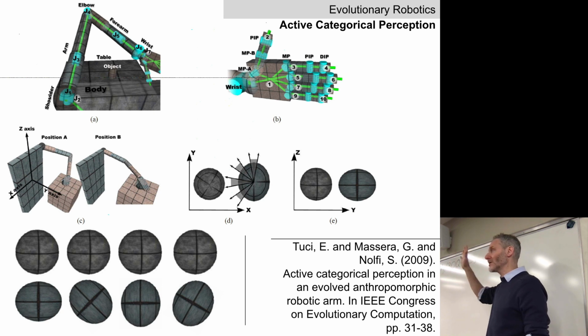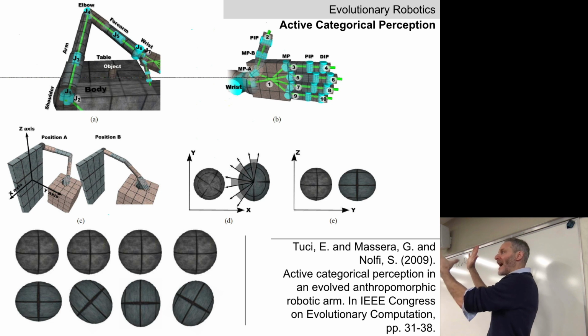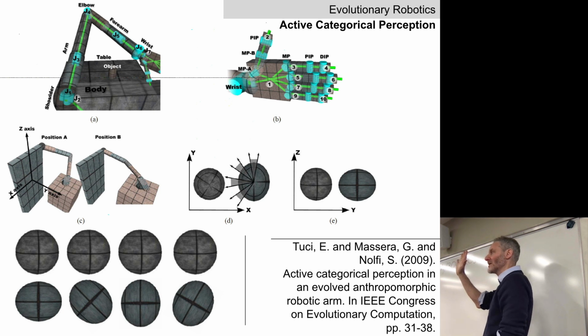So far, so good. So you can imagine coding this up in PyBullet, in PyroSim. 15 motorized joints. In everything we've seen so far, there was always one motor neuron assigned to each motorized joint, right? In this case, there's one motor neuron that fires, and whatever floating point number is coming out of the motor neuron is copied 15 times and sent to the 15 motorized joints so that they all apply identical torque, which causes this. This robot cannot move its fingers independently. Make sense?